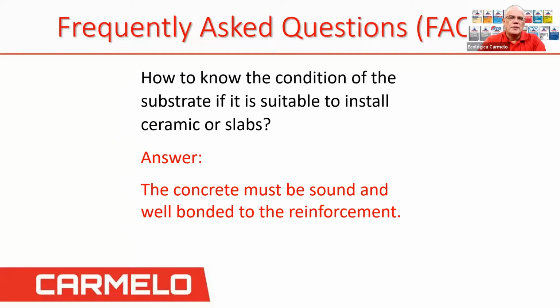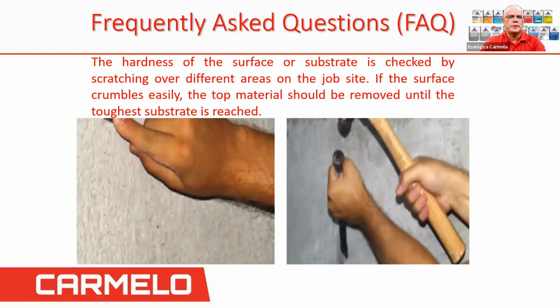How do you know the condition of the substrate is suitable to install a ceramic or slab? And the answer is the concrete must be sound and well bonded to the reinforcement. So that's very important.